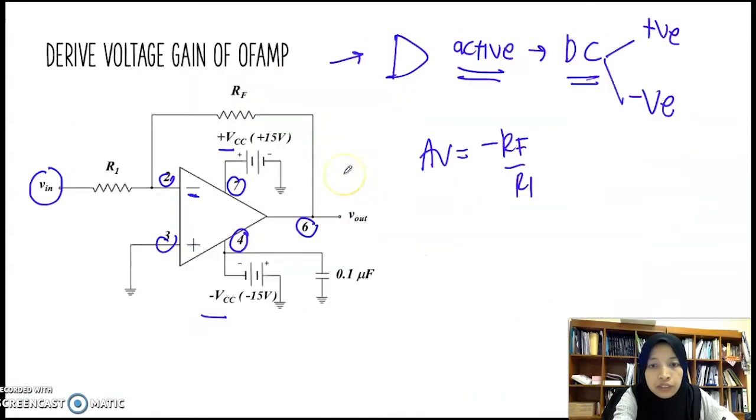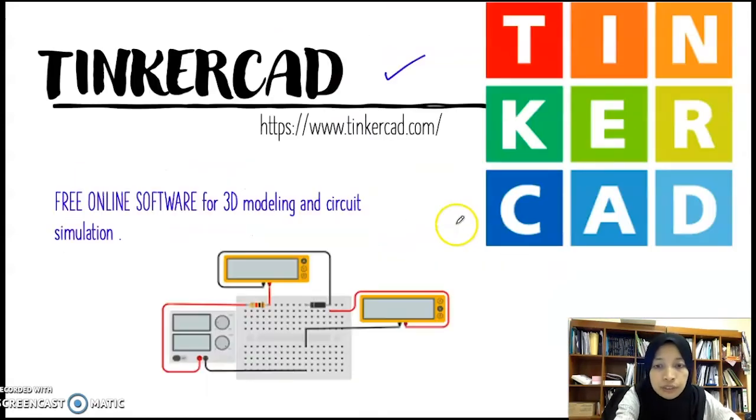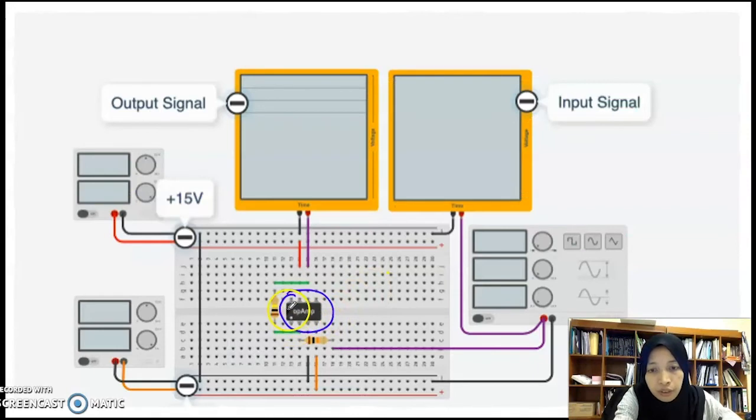Like shown here. Let me open. Yeah, this is the dedicated number for each pin. So you need to follow this one. The semicircle here denotes that this is pin number 1. If you look at your chip, you can also see the semicircle here. So this is pin number 1, 2, 3, 4, 5, 6, 7, 8. So please identify the pins correctly.